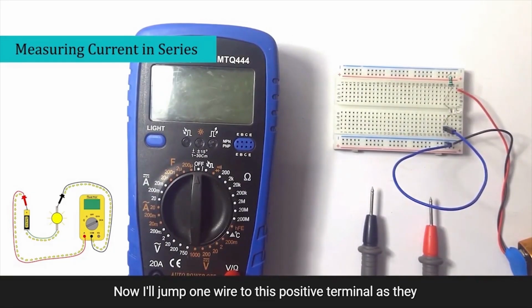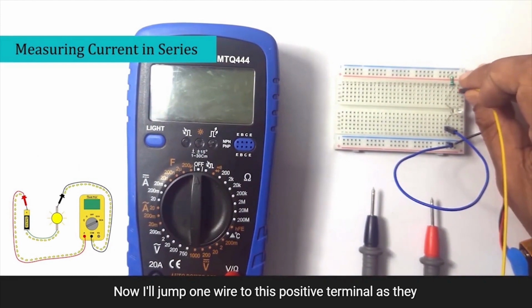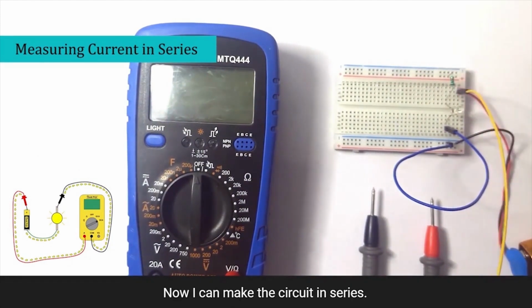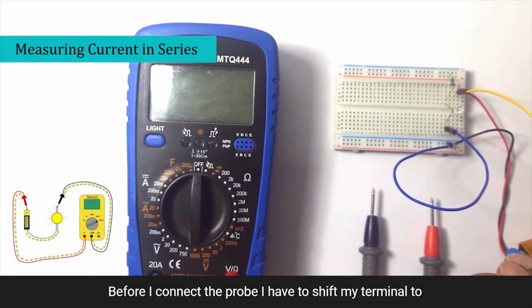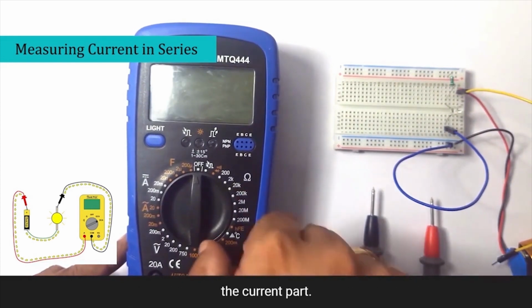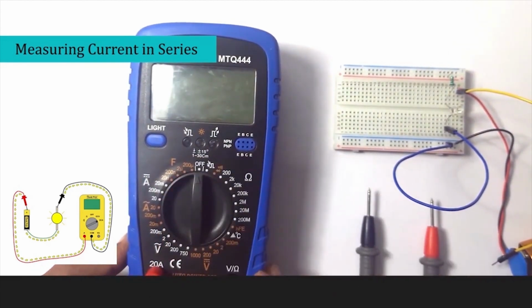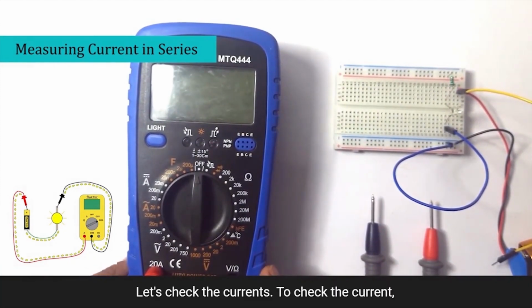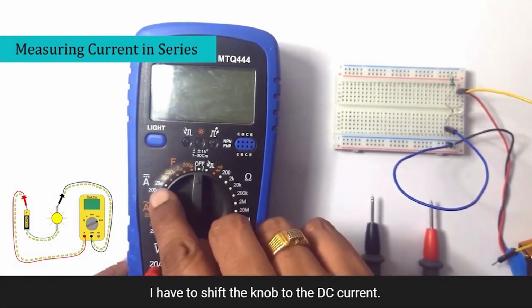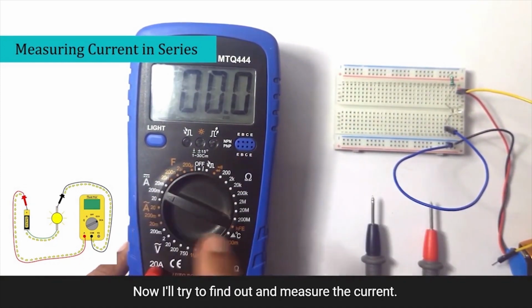Now I will jump one wire to this positive terminal. As these are connected vertically, now I can make the circuit in series. Before I connect the probe, I have to shift my terminal to the current part. Let's shift the terminal to the current part. Now we have shifted our terminal to the current part. Let's check the current. To check the current, I have to shift the knob to the DC current. I'll switch backward. Now I'll try to measure the current.